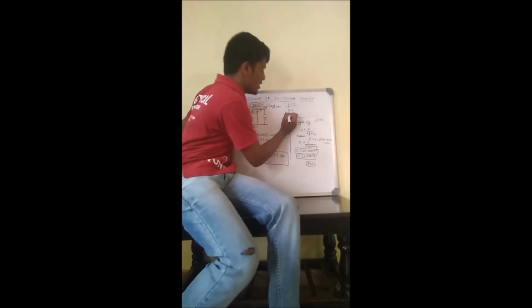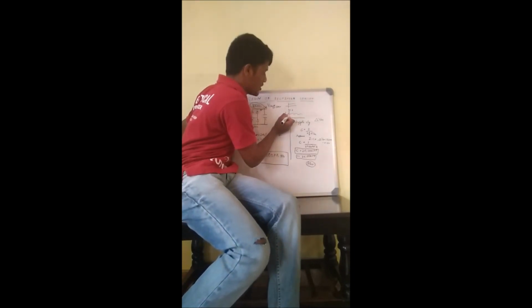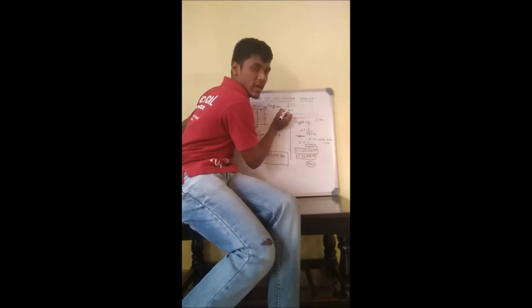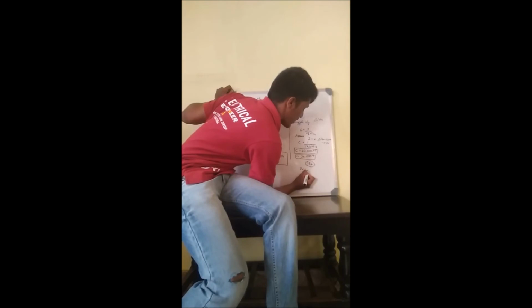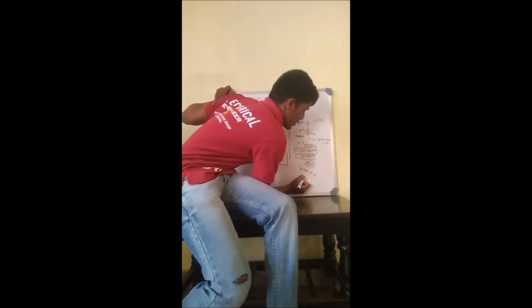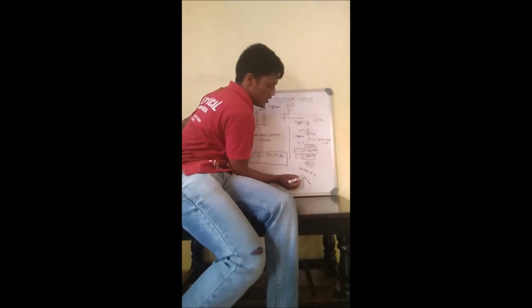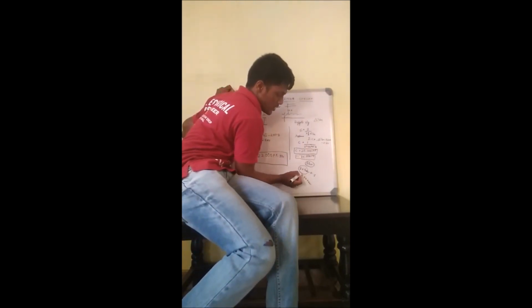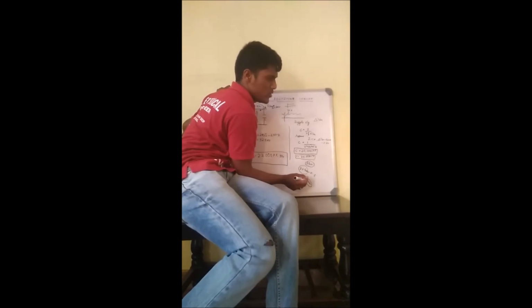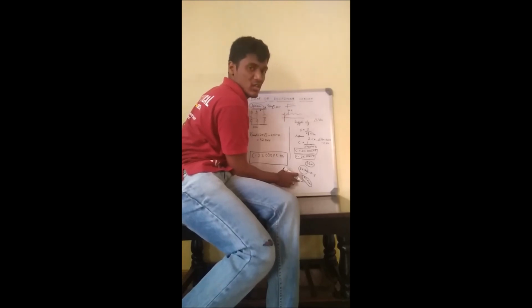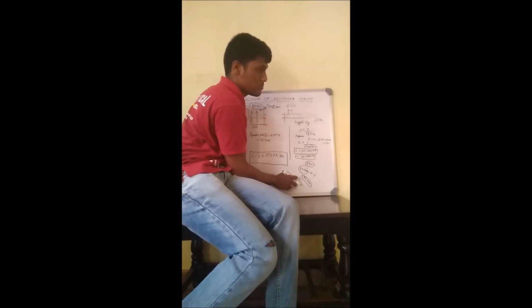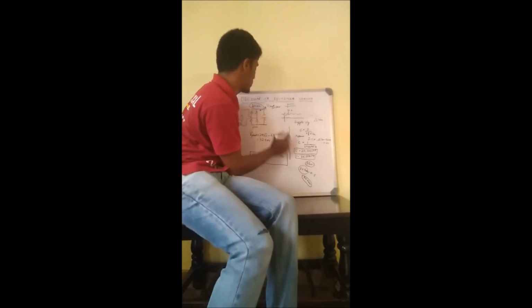So what would be the least voltage here? Since I assume this peak value is 32.5, to calculate this least voltage, we need to subtract the ripple voltage. 32.54 minus 0.5 will be around 32.04 volt. So the voltage will be varying from 32.5 to 32. This variation is very small, but some people won't entertain even this type of variation. In such a case, to maintain the stability of the output voltage, it's better to add a Zener diode in parallel to it.